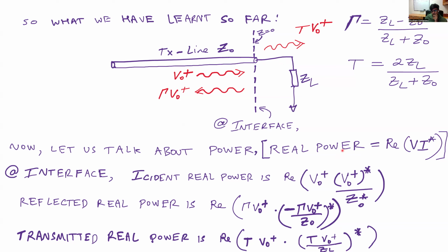As you know, power is a complex quantity because the voltages and currents are complex quantities, and power is just V times I. So the complex power S can be written as a real part and an imaginary part, because the complex power S is defined as the complex voltage times the complex conjugate of the complex current. And therefore, the real power is just going to be the real part of the complex power, so it's going to be the real part of V I complex conjugate.